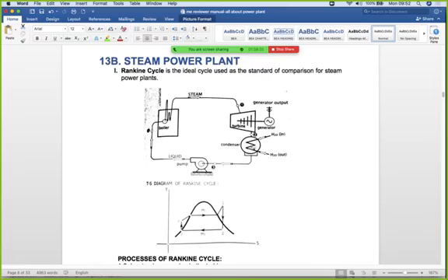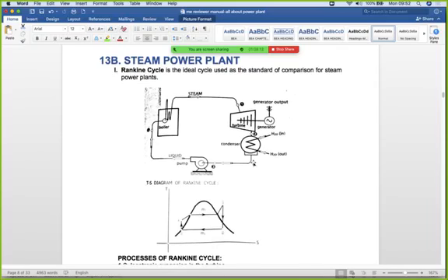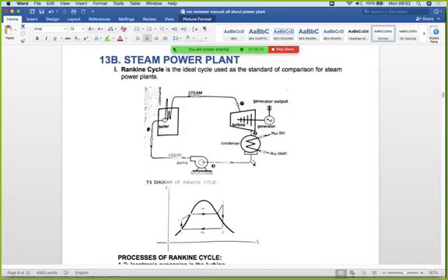Of course the cooling system provides water. So it goes back to its original state of liquid, and it will be pumped again to the boiler in the form of makeup water. With that, it continually supplies the boiler, constantly providing the minimum, if not the maximum, level of water inside the boiler. So that completes the cycle.